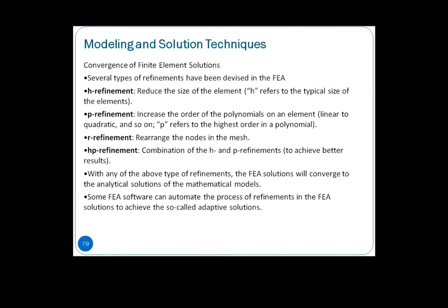Some software also has this automated refinement processor. Here we call it adaptive meshing or adaptive solutions. Later on in our examples, you can see that we also make use of this adaptive meshing to help us refine. Basically, it's more towards h-refinement, reducing the size of the element to get a more accurate result.